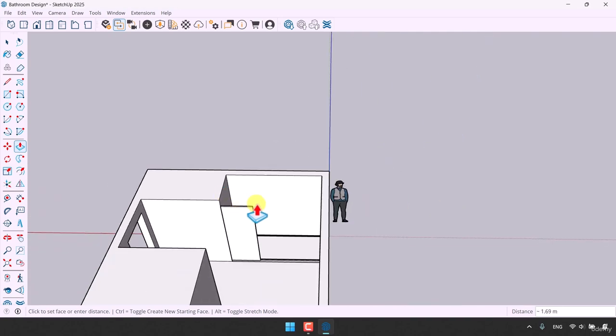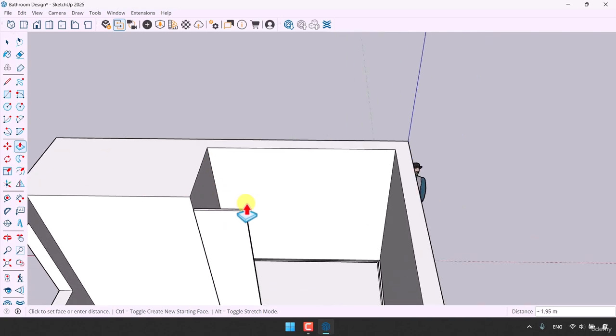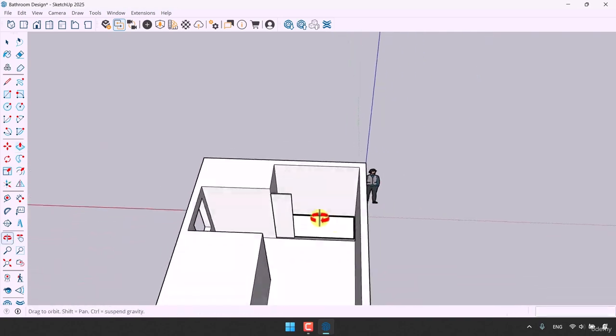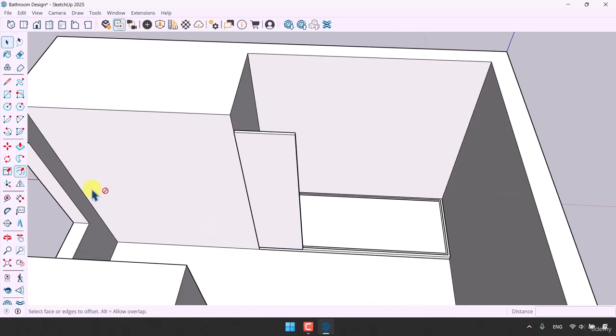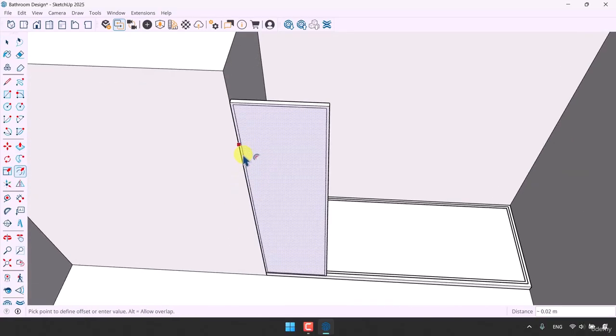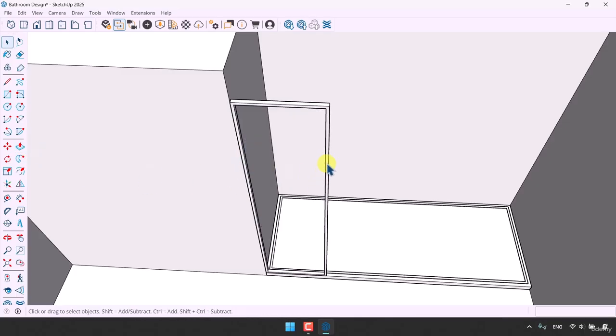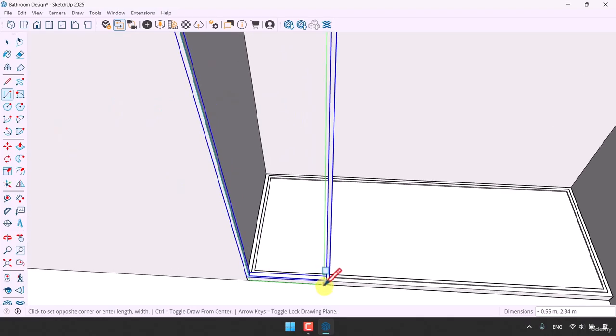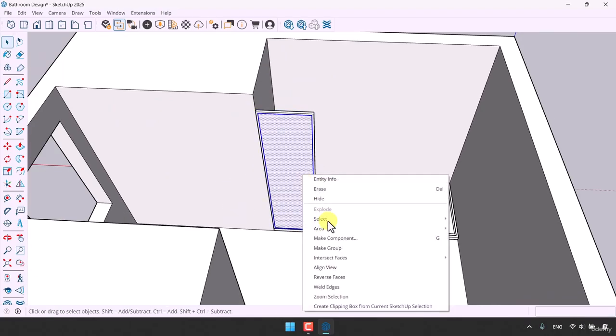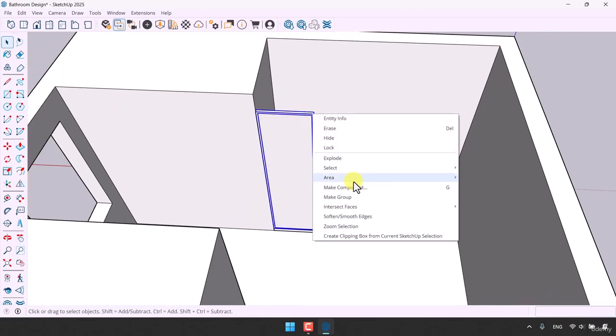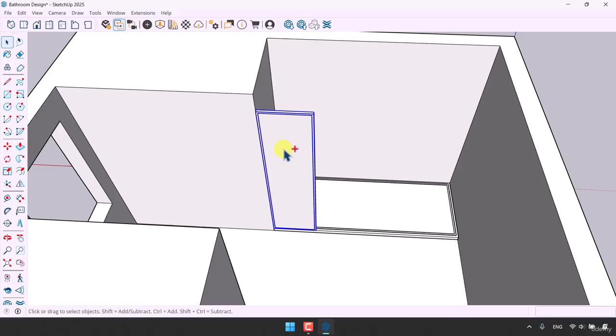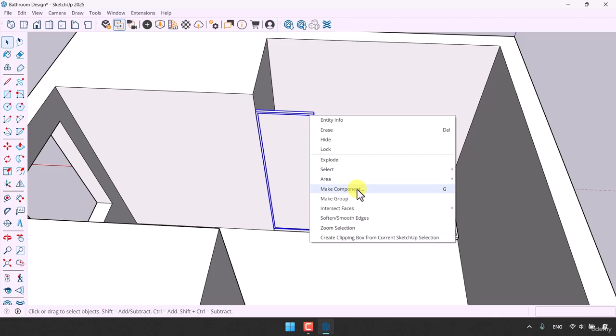So I want to generate the doors with glass. So in this case, I'm going to type 2 here. Click on the Offset, draw my offset, 2 centimeters for it. Push/Pull, extrude it. Now I'm going to convert it to a group. Click on the Rectangle, draw a glass, click on it, make a group here, make a group again. I can press Ctrl+Z, select this and select this, and because I want to take a copy, I can make a component. This is the better option.